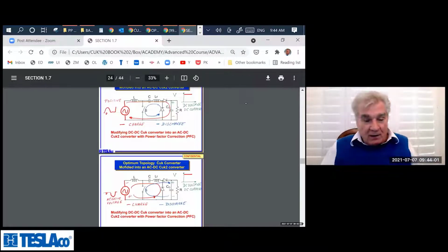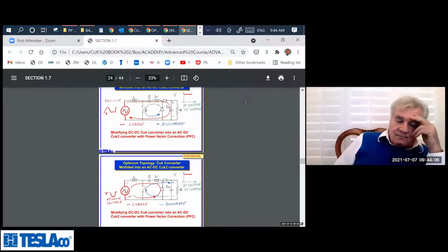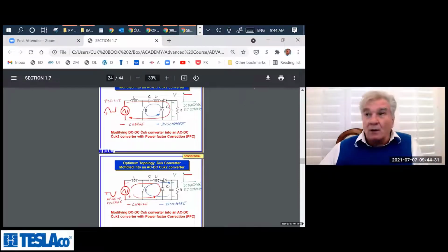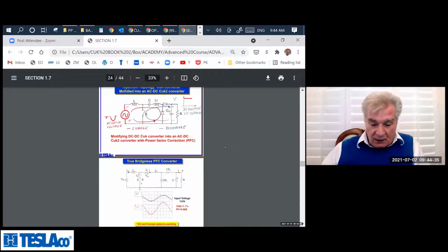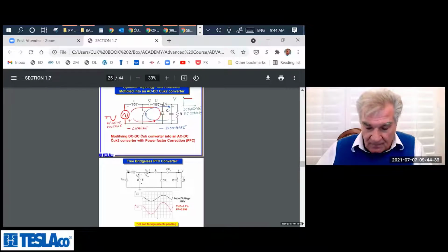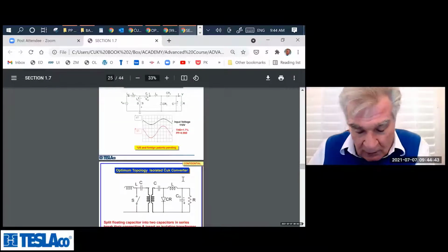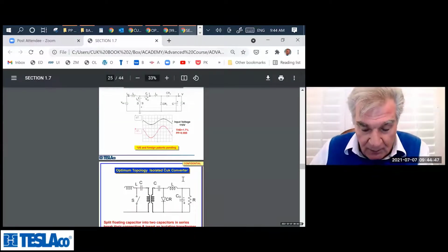So really, now you have, and I introduced this way back then. I think in 2011, I published a sequence of four papers from June till December that year in the Power Electronics Technology magazine, which was at that time a print edition. I introduced the power factor correction there, and all the demonstrations, and here is some summary of that. Here is the non-isolated version operating the power factor correction. Input voltage comes to 10 volts, and total harmonic distortion is 1.7%, and power factor is perfect, almost 0.999, right?